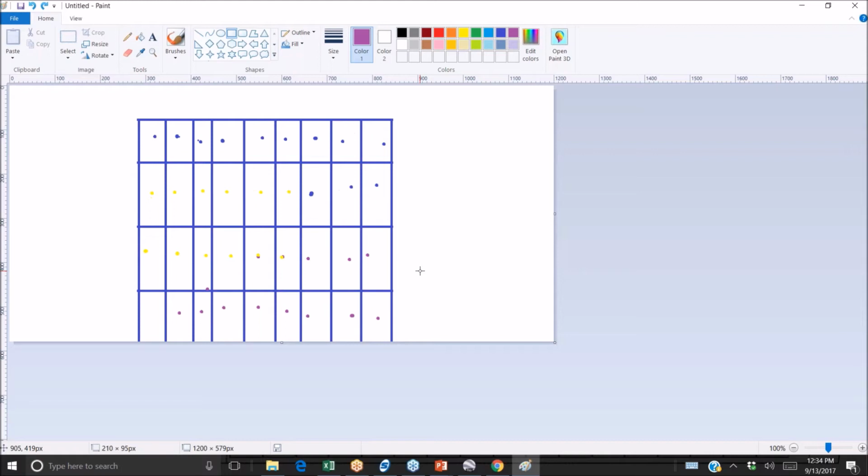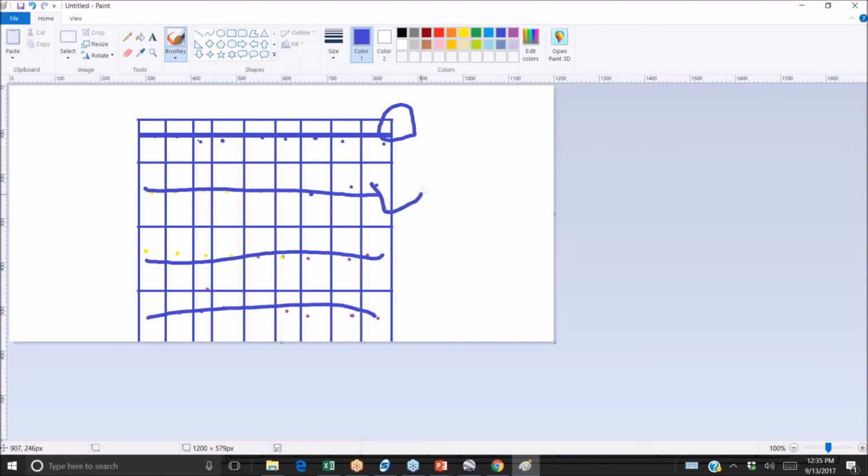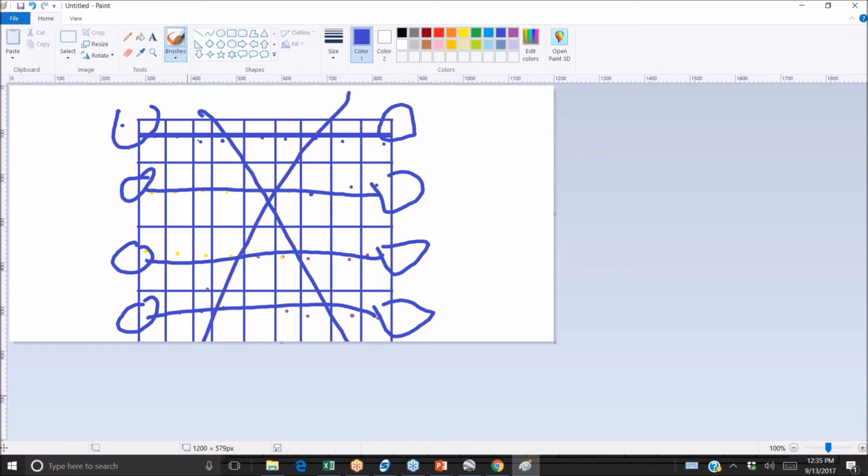And so lately, when I've been doing my solar design, I might take a step back and say, well, do I have to do 3 circuits of 12, or can I do 4 circuits of 9? Because if I can do 4 circuits of 9, I can have my circuit 1, and then my circuit 2, and my circuit 3, and my circuit 4, and have my connectors all accessible at the edges of the array. And for that matter, I'm looking into multiple power point tracking string inverters so that I don't need to have any module level electronics inside the array.